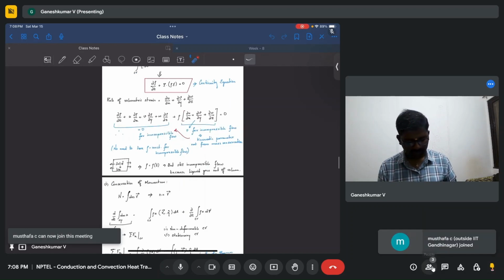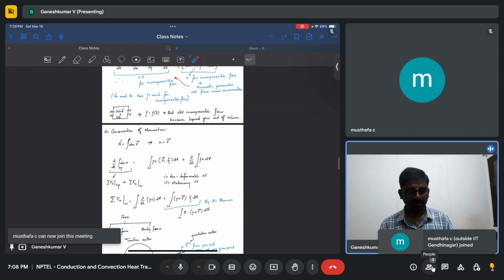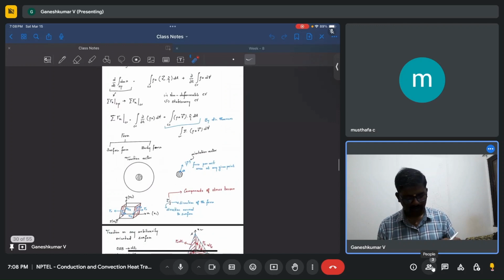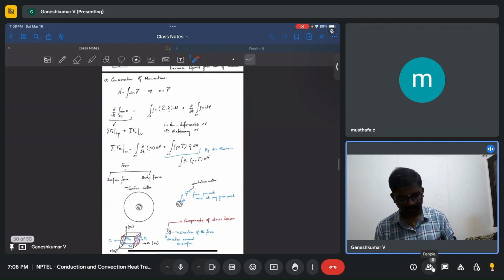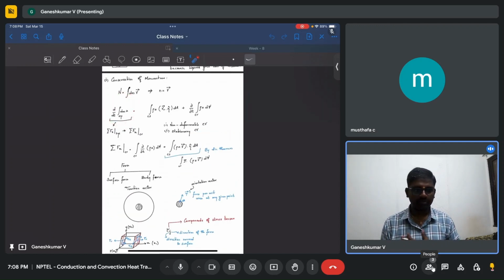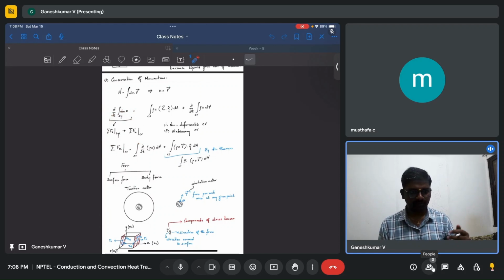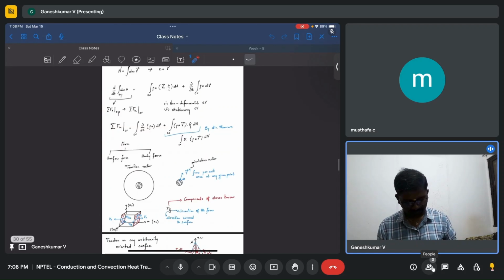And then we carried out the momentum conservation equation. Basically N is momentum and small n is velocity. It's a specific quantity of momentum, and we derived the momentum conservation equation. For example, we have this external force acting on the system, and this force can be divided into surface and volume forces, or body forces.